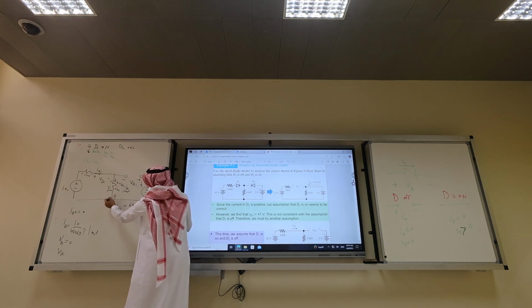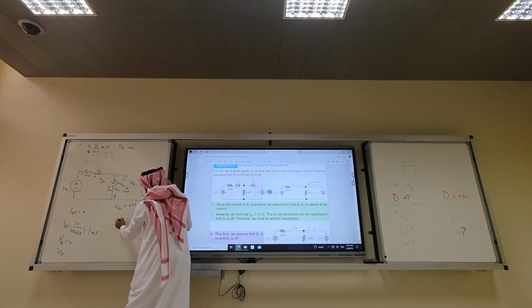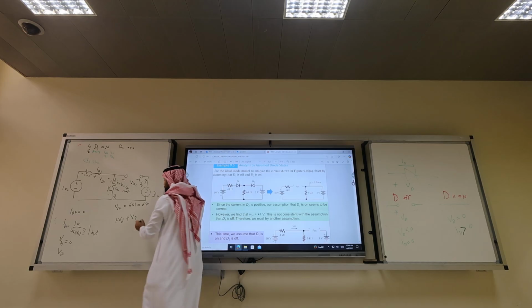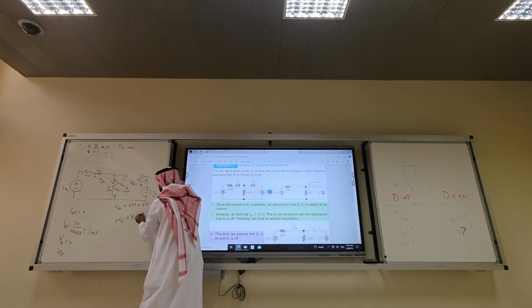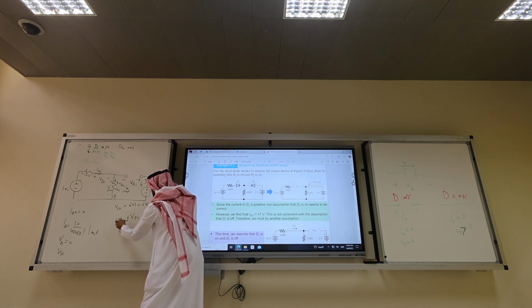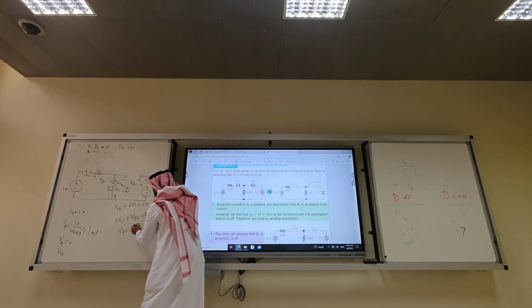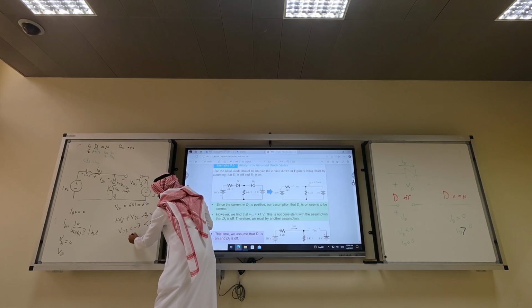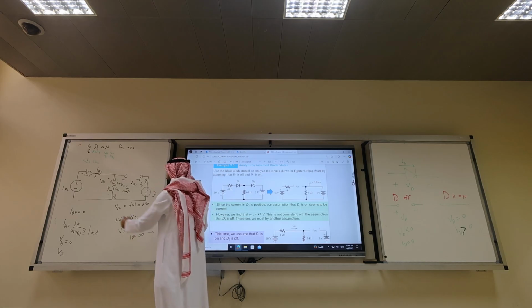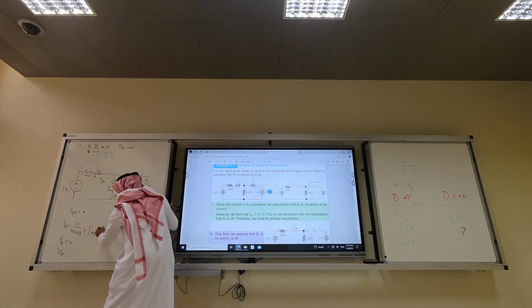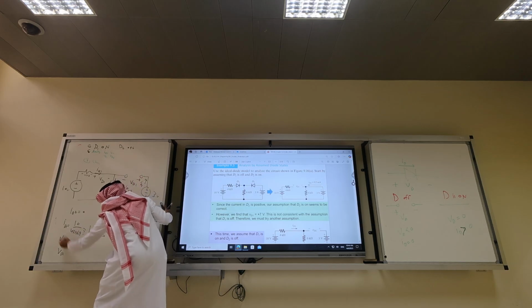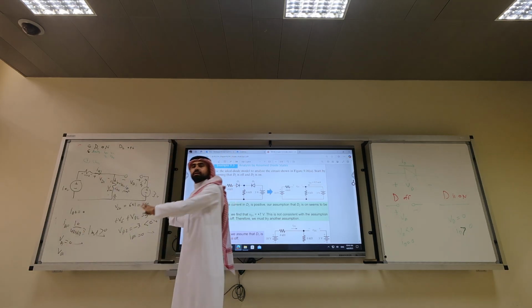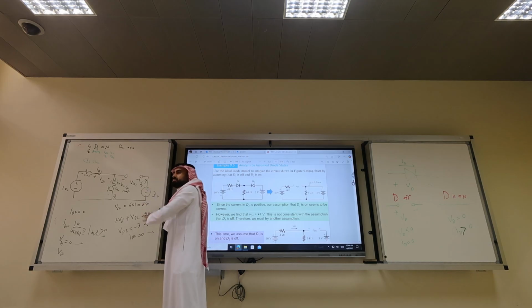I want to start here. Voltage rise plus V6, minus VD2, voltage drop, minus 3. So what is VD2? Minus 6 minus 3, it's minus 3. Is it less than 0? Yes. Is ID2 0? Two conditions satisfied. Is ID1 greater than 0? Yes. Is VD1 0? Yes. 4 conditions are satisfied. Then this circuit is correct.